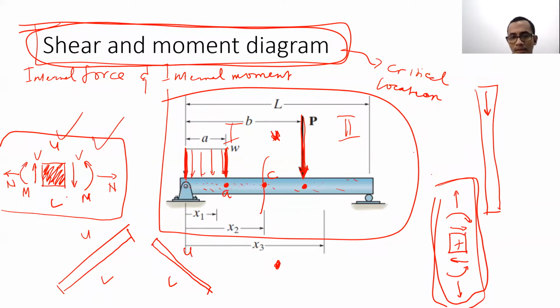Actually, there is no sign convention for that besides the horizontal beams. But in order to make it easier for you, when you want to do the shear and moment diagram, the first thing you're supposed to do is draw the positive signs like this. Okay, Matthew? Okay, sir. For the tilted one, how do you determine which is the positive x direction?